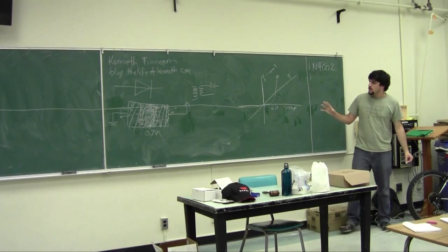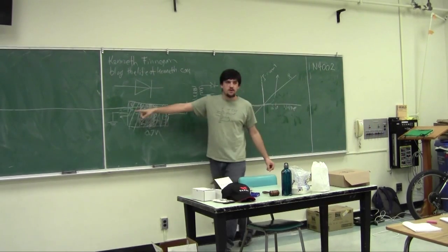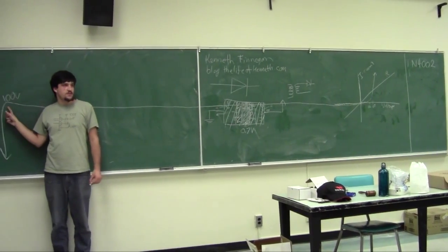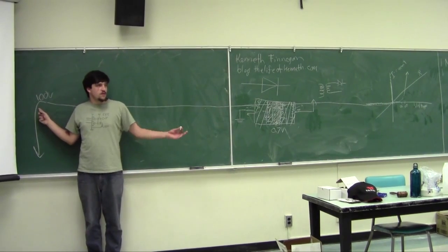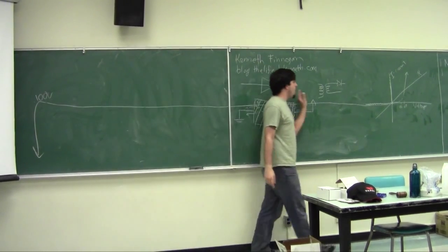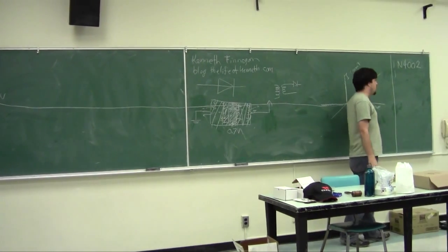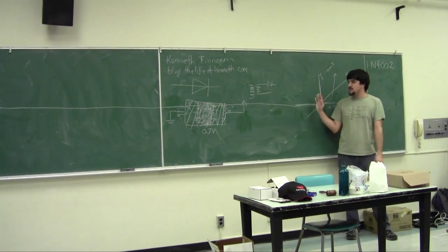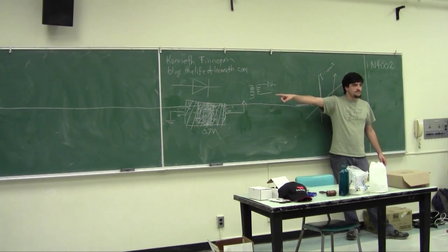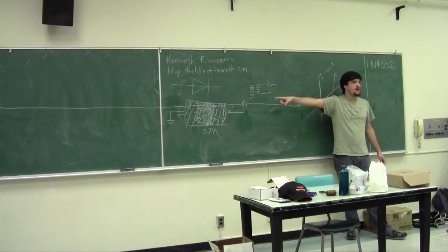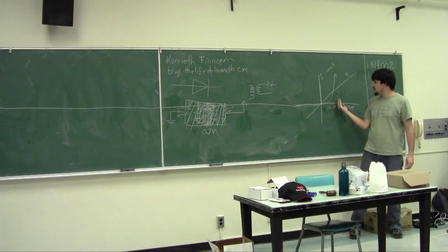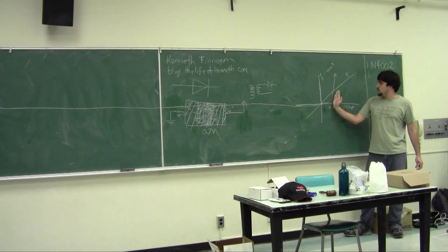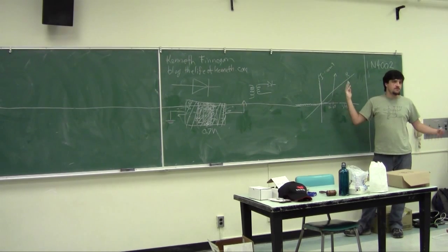But you don't always care about this part, right? This is useful when you're dealing with high voltages like in your wall, but sometimes you don't really care about that, and you only really care about this part right here, and that's more important. And that's called a small signal diode. Because a power diode is useful over there, because it blocks a tremendously high opposite voltage. Small signal diodes only are so interested in this small section here and are most useful just because of this need for various reasons.